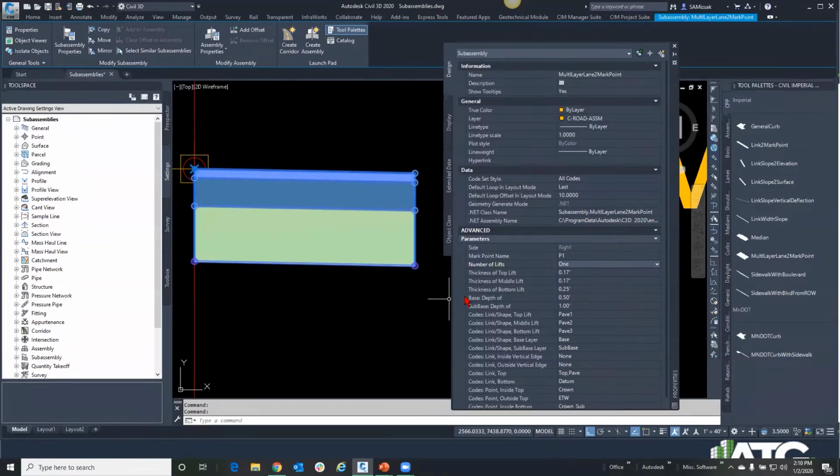And we don't want to use that generic pavement structure. We want to use something that is 1 entity. Maybe you're building a trail and it's just flat out. We're dropping in 3 inches of blacktop. We're running a paver over it, a packer over it, and we're done. It's 1 lift. Well, I don't want to zero out one of my lifts out of the box lane. So just by going to 1, I get that capability.